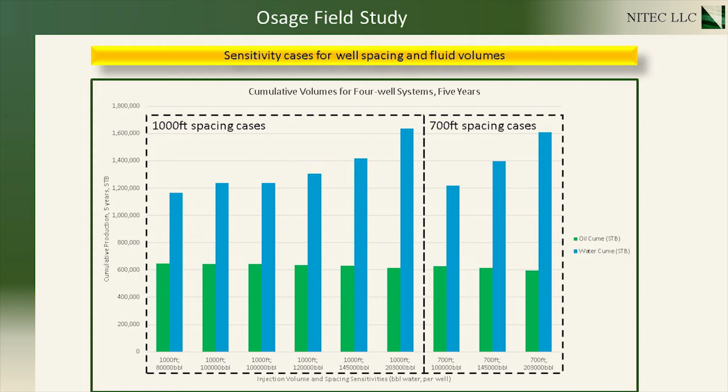The wells at the widest spacings and the lowest injection volumes performed the best in terms of oil EUR. In fact, since the best case is at the leftmost extreme of the parameter space, this chart suggests that the optimum well spacing is even wider and the optimal injection volume even lower than what is explored here.